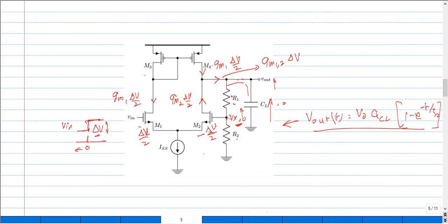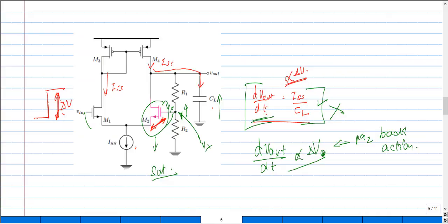So if our amplifier is supposed to amplify a sinusoidal input, let us assume a particular signal here so that it becomes clear. Let us assume that our amplifier is supposed to amplify a signal given by V naught sine omega naught t, and this is the input signal. What should be the slew rate of our op amp so that this input signal is amplified without entering into a slew mode?